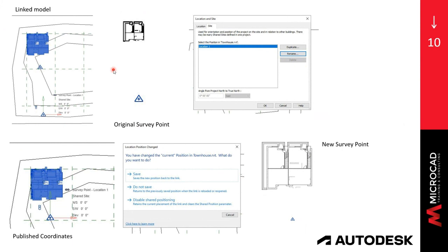So I hope this all gives you a little bit more of an insight of what the survey point does, what the project base point does, and what this whole thing that seems to be a little bit obscure when you're in the designing phase of the project. But general contractors, I'm sure they will be very happy that you start understanding this so much better, because they need to position their projects properly in the world and in height. So, having said all that, I'm going to open the floor for questions at this point.